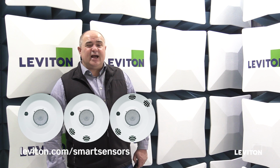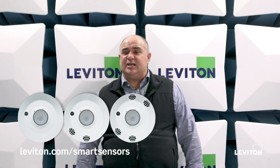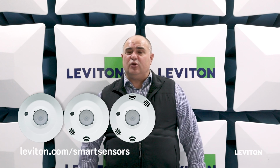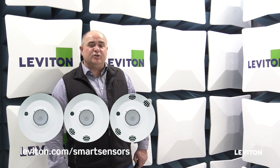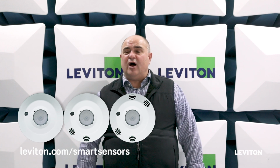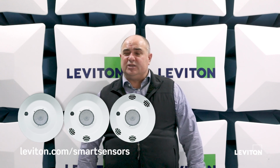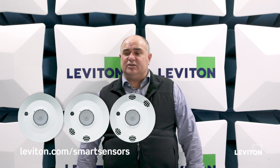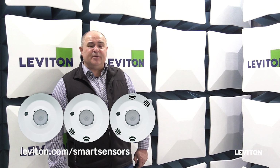And then, as we pointed out, it does have occupancy sensing and vacancy sensing ability. The room controller version does have 0 to 10 volt dimming, as well as the partial on and partial off abilities. It does have on-off switching only with the ceiling mounted sensor, as well as the daylight harvesting with the smart room controller, and then the ambient light hold off feature with the ceiling mounted sensor.